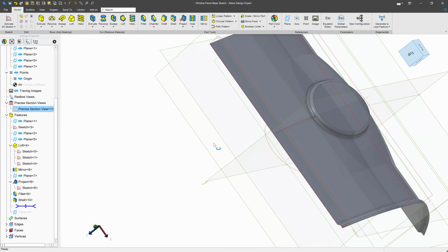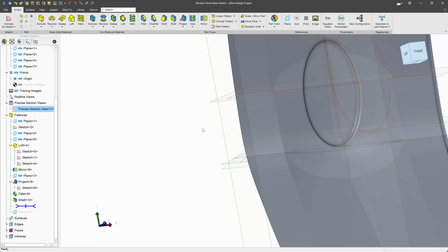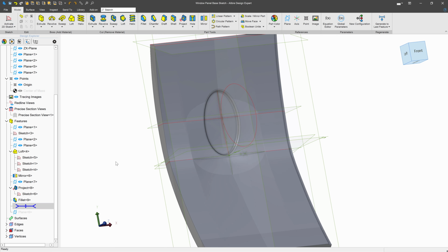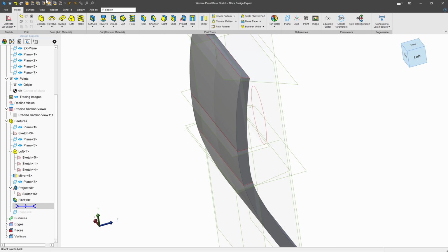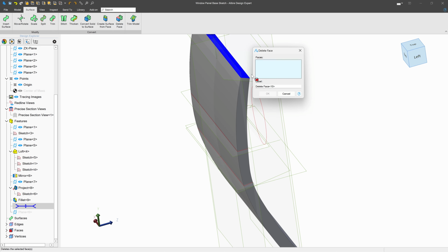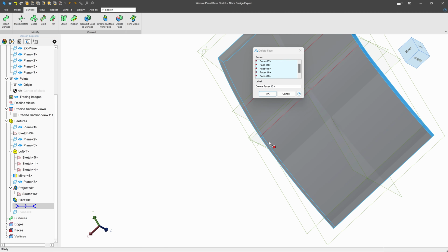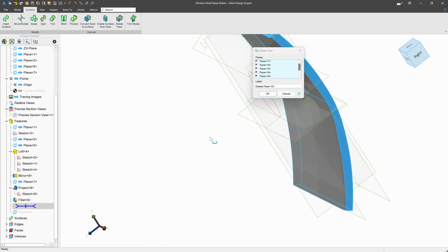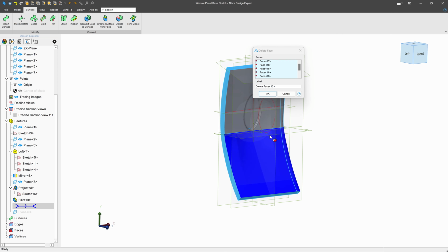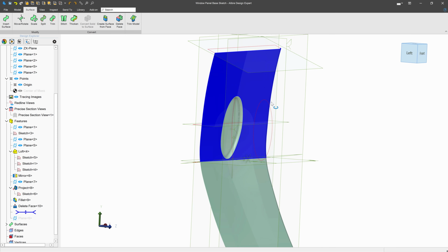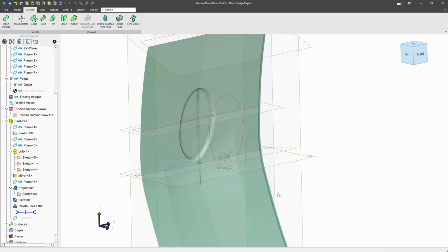I want to go through another method of doing this though, because when you're working with surfacey features like this, sometimes you want to have more than one option. So let me delete the shell. And this time we'll go with surface and delete face. And of course the surfacing is available in professional and expert, if I recall correctly. And now that I've selected all the faces that I don't care about being constant thickness, I'll select OK, and of course we are taken down to an infinitely thin surface, which is really only a